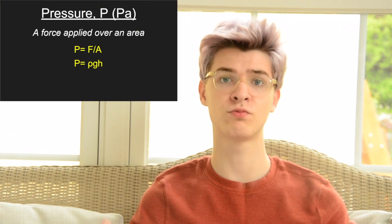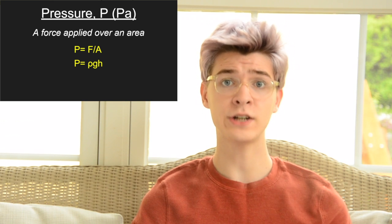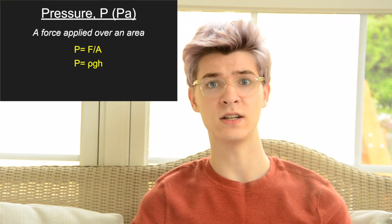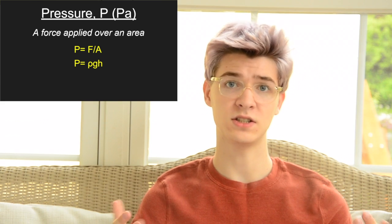Now, these definitions of pressure can be used in any scenario. However, there is an equation for pressure that only works with fluids, and that is P equals rho g h. The P in this equation represents our pressure, the rho represents the density of the fluid, the g represents our universal constant of gravity, and our h is actually the depth at which the object is submerged.